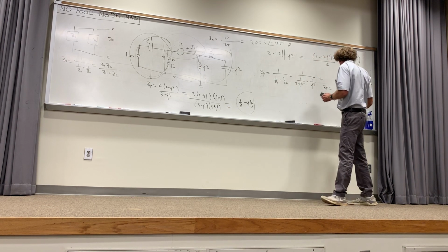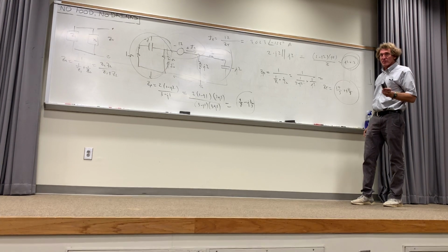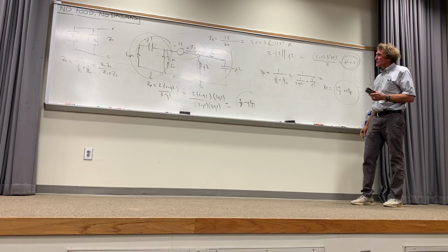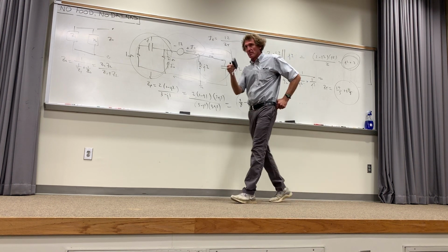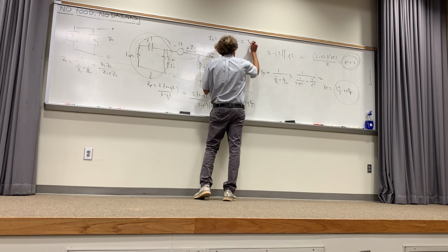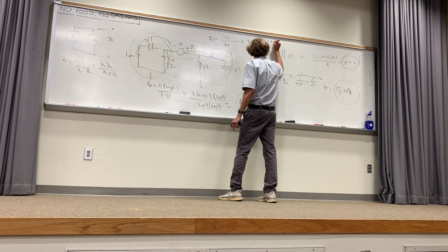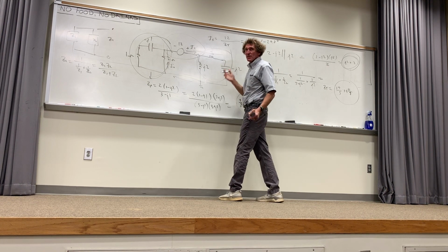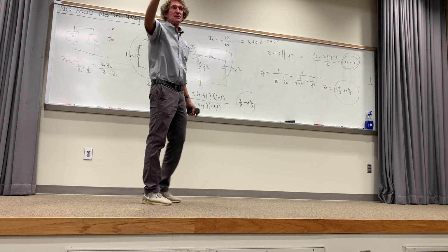If this is the total impedance right here and you divide it into 12, that number should be something we all get rather easily, right? If that's not it, let's get the right answer. Can somebody do that for me? Go ahead. I got 3.72 at an angle of negative 29.7 degrees, roughly. How many got that? All right, you're doing it right. Make sure you can do these things efficiently.